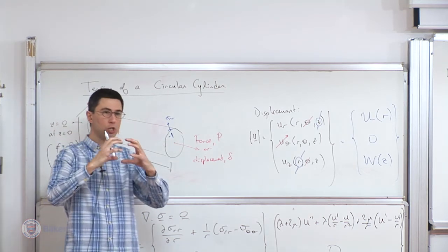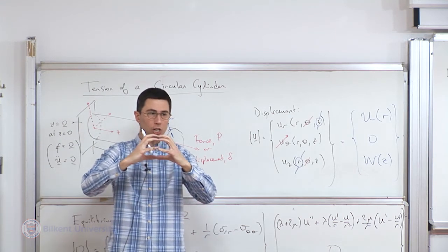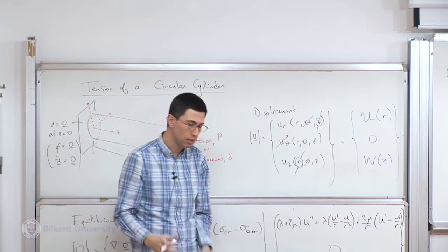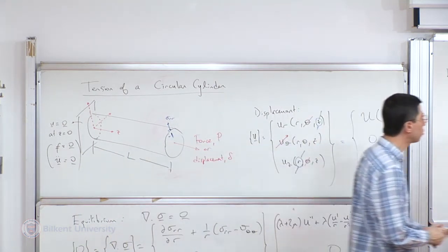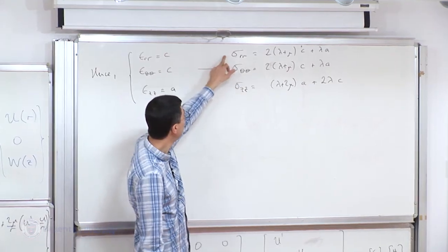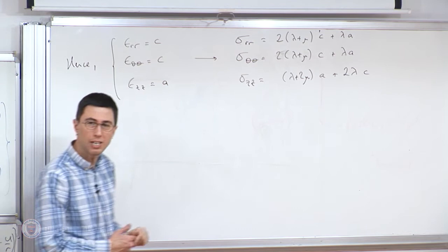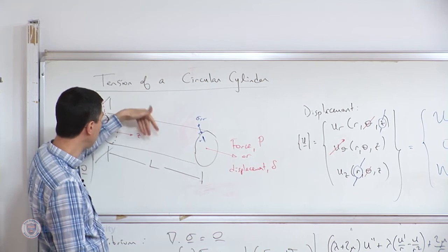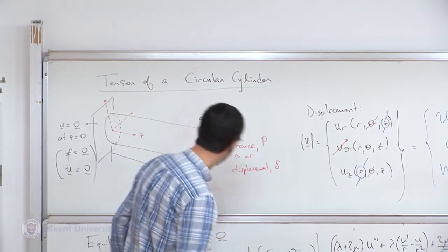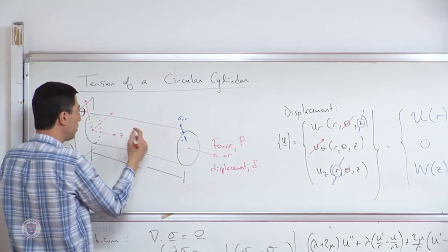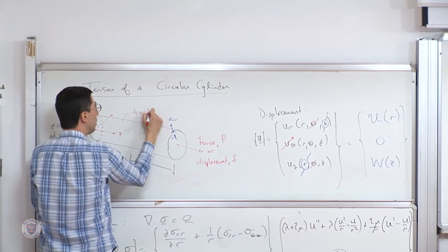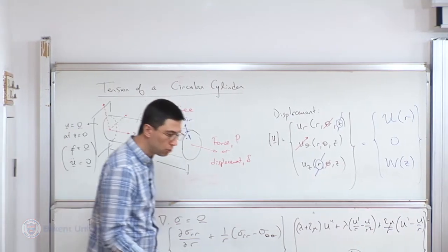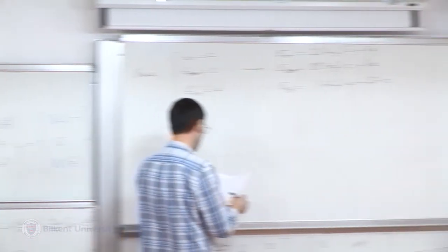For instance, if I had a pressure vessel, remember, we had tangential stresses that under the pressure try to keep the vessel intact. That's a sigma theta theta. We don't have such a scenario here. So sigma theta theta should also be equal to 0, but they're equal to each other. So it's easy to see immediately that sigma RR should be equal to 0 on the surface, because it's a traction-free surface. Some things are not explicitly indicated, but it is clearly traction-free, okay? And that enforces sigma RR to 0, and sigma theta theta is equal to that.